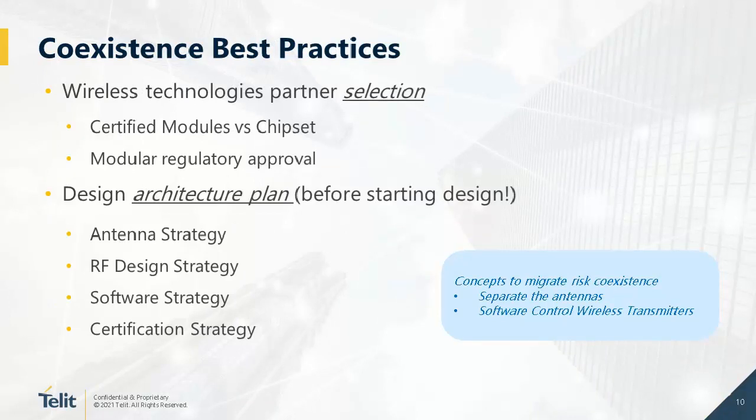Okay, so best practices. One of the things we want to mention today, and Steve touched on this, is using a pre-certified module, no matter what wireless module, whether it's Bluetooth, Wi-Fi, cellular, Zigbee, Z-Wave, whatever it is, if it already has FCC approval, the regulatory approvals, the ISED or the IC approval for Canada, is one thing.